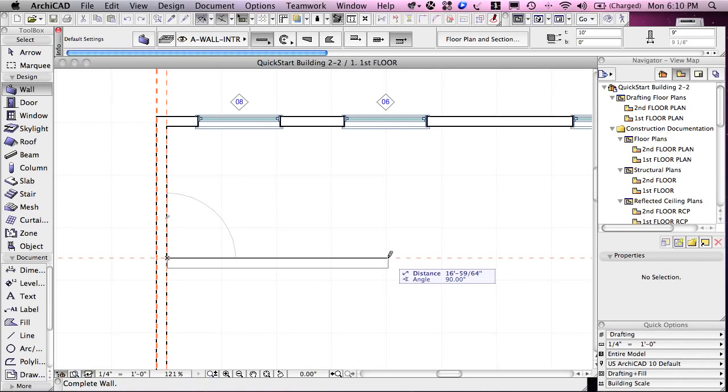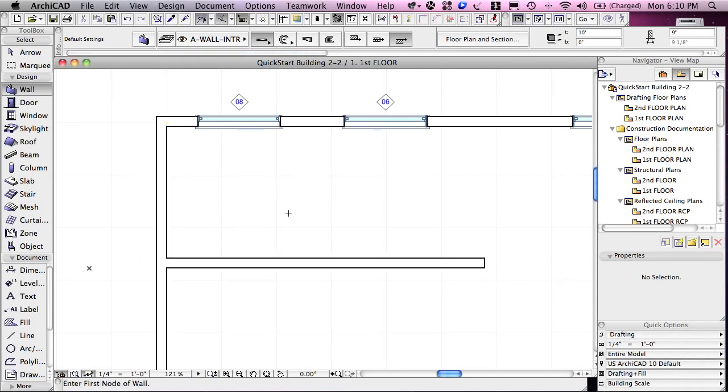And now you can see that the preview of the wall is correctly placed down below the heavy line, which is the reference line. Now I can do this a very specific distance, or I can just gesture, and in this case, I'll just sketch out that this room might be wide enough to have these 2 windows included. Now I had this set up for a single wall rather than a chain, so it finished constructing that one wall when I did that.